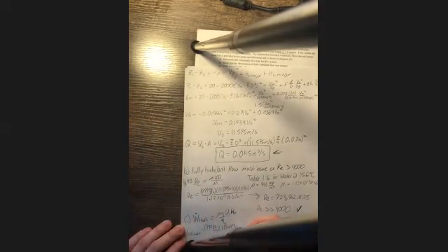All right, now we can start plugging things in. 999 kilograms per meters cubed times 9.81 meters per second squared, times 0.045 meters cubed per second, times head of the pump, 15.95 meters, all over 0.7.